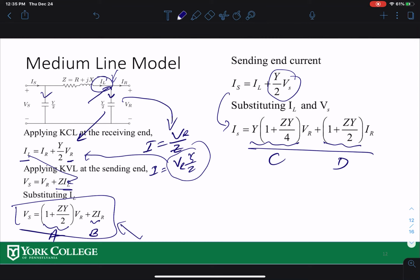Then for the sending end current, IS equals the current going into this branch as well as the current coming here. So IL plus Y over 2 times VS. Again, when you have admittance, you multiply with the voltage to find current because it's the opposite of impedance. Then if you substitute IL, IS and VS, you will find this equation for IS. Now if you compare with the ABCD constants, this is your C, this is your D, this is your B, this is your A.